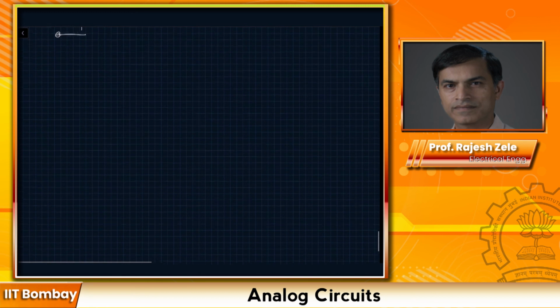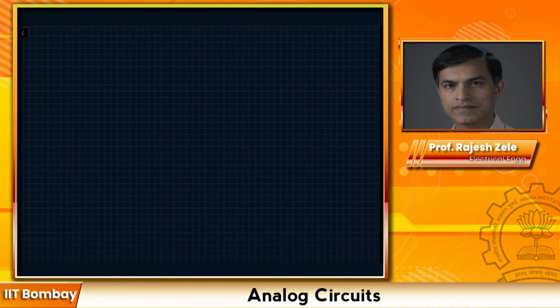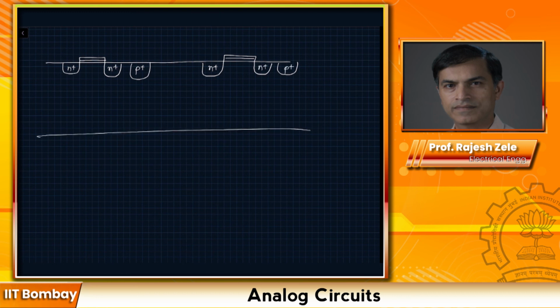So when we look at a standard digital CMOS process, if you remember, I had asked you to draw the cross section. Let's say you may have one transistor which looks like this, and then there is a bulk here, and you may have another NMOS transistor that looks like this, and it has its own bulk. So this is N plus, N plus, P plus, N plus, N plus, P plus. And this is our substrate, P minus substrate.